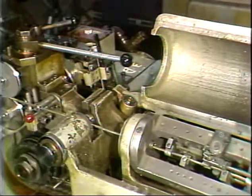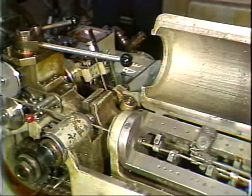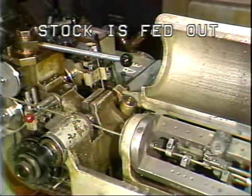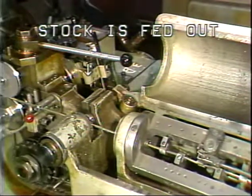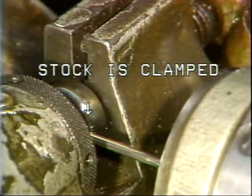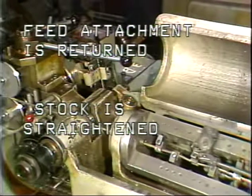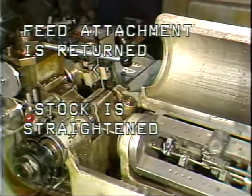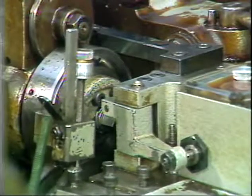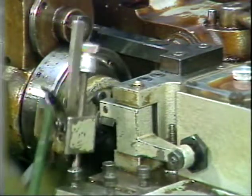Also timed with the stock feed system is the action of the stock straightener and stock clamping jaws. As the stock is fed out, the stock clamping jaws are unclamped and the slide will be in its forward movement. At the start of the return portion of the feed cycle, the clamping jaws will clamp the stock and the slide will begin its backward travel to straighten the stock. The return of the stock feed attachment and the cutoff of the finished part and the backward travel of the slide all occur during the return portion of the feed cycle.